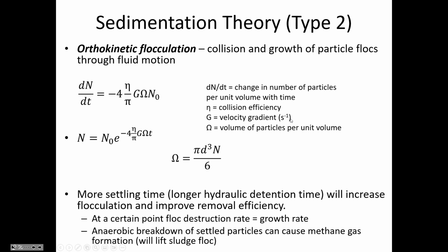And you remember that when we were talking about flocculation in drinking water treatment, we had decreasing G values in successive flocculation basins. Maybe we started with a G value of 85 inverse seconds, then down to 50, and finally 20 in the last mixing chamber. But in a single clarifier, the mixing energy is just about how much velocity is in the water because of the particles settling themselves and vacuuming out the sludge from the bottom.